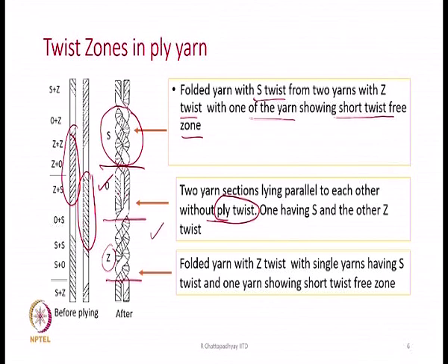So, this is what is required to be done. What has to be done is what we have discussed till now. Now, the point is how we are going to achieve it. That is what the machine is going to do, so we will now discuss how this is being done. First of all, what has to be done, why it has to be done, and the next question is how we can do it. These are the three important questions that should always come to mind: what we should do, why we should do it, and how we should do it. What has to be done is that there has to be a phase shift. Why should we do it? Because phase shifting is going to give us a yarn which will be strong.